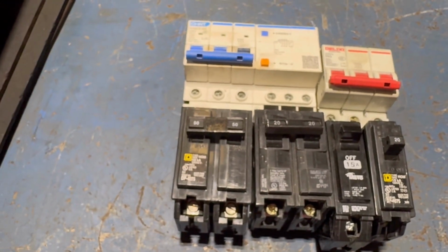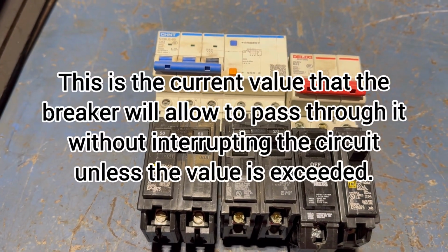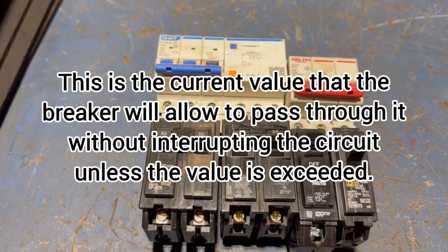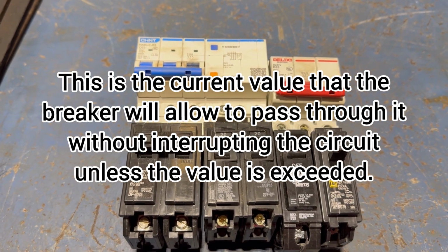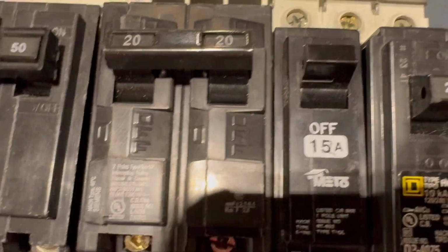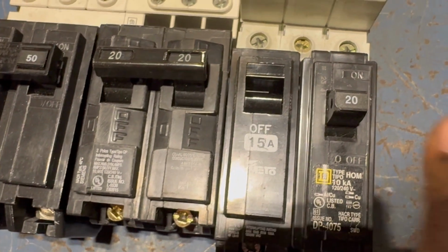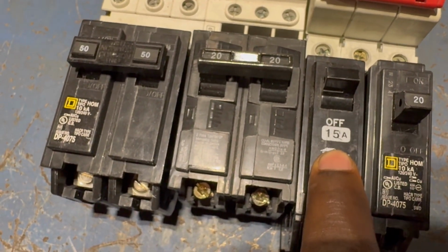The next thing we will go through is the rated current. The rated current is the current value that the breaker will allow to pass through it without interrupting the circuit unless the value is exceeded. For instance, on this 15 amp breaker right here, the rated current is 15 amp.